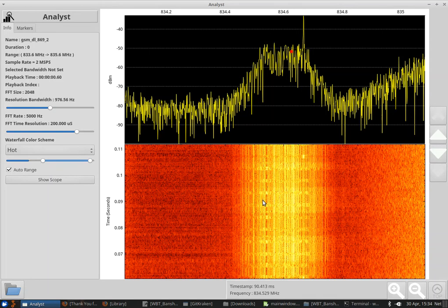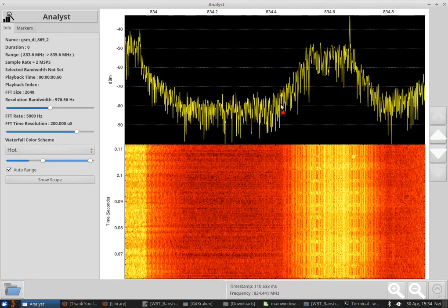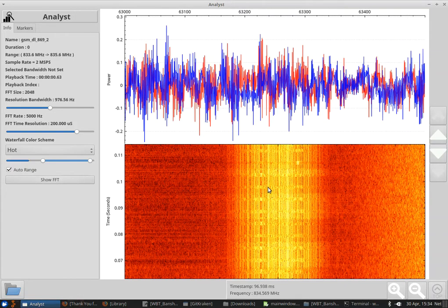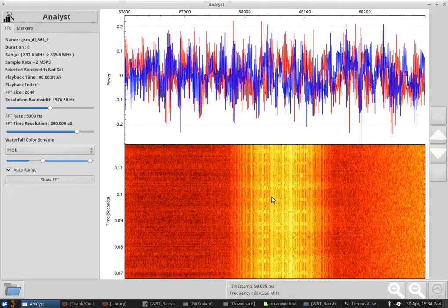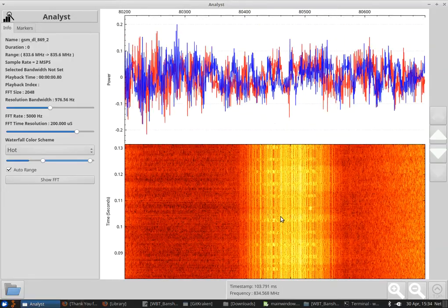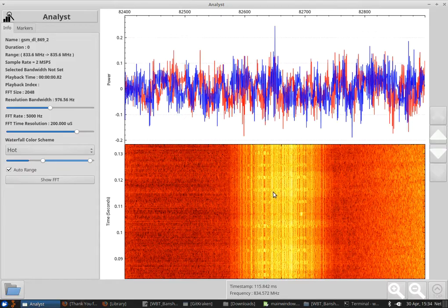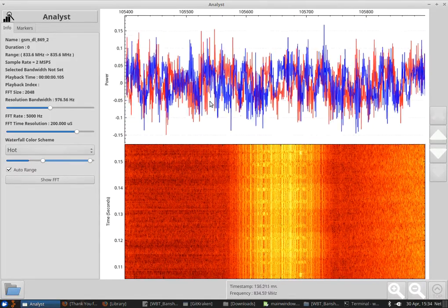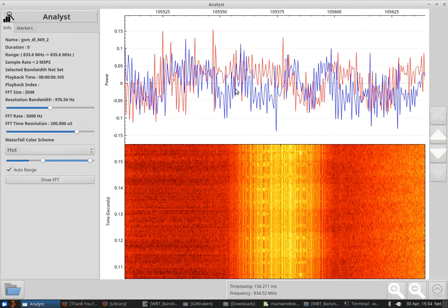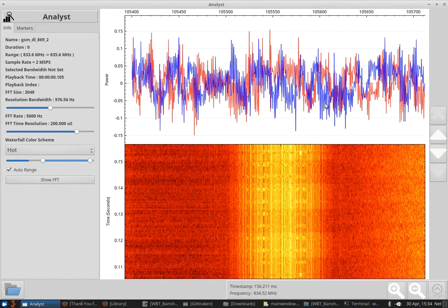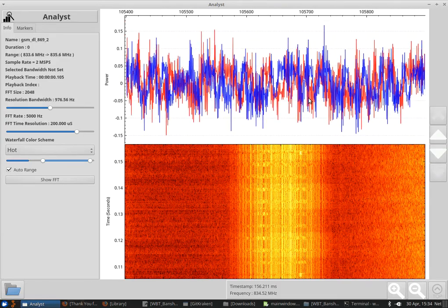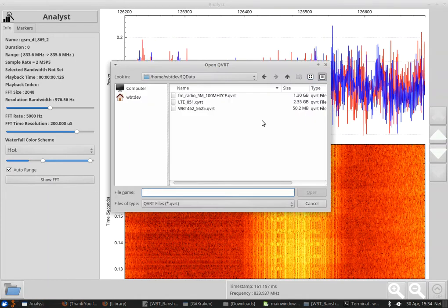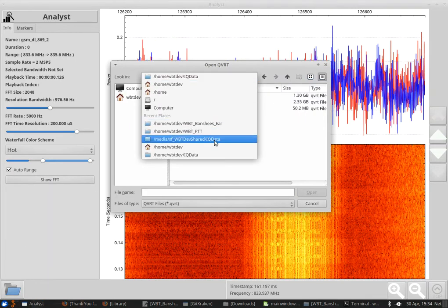What we can additionally do is, instead of showing the FFT graph up here, we can show a time series of the IQ data itself. Currently, it's just displaying the first 1,000 samples at that sample index. However, when we move to certain features inside the file, you can see the pattern of the IQ data change. Also shown is the characteristic modulation type of the GMSK here, as seen inside the IQ. This is good for taking a look at short-featured bursts as well.